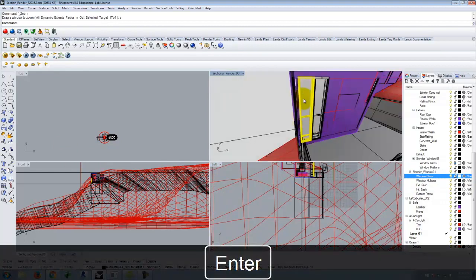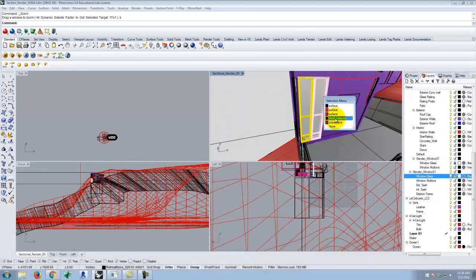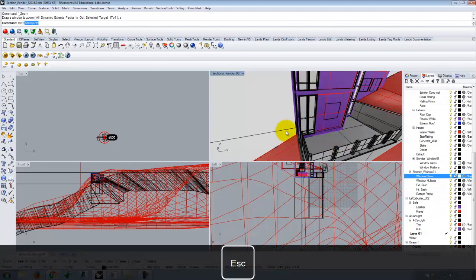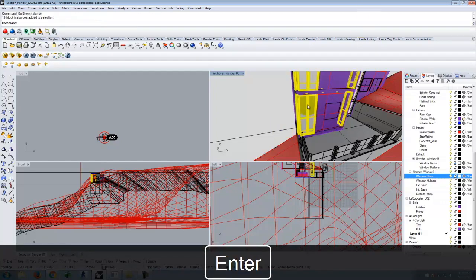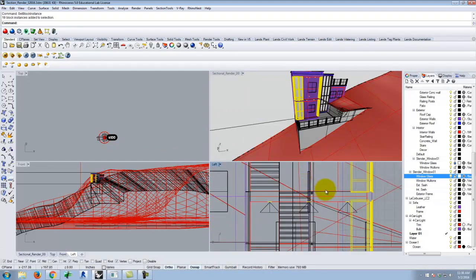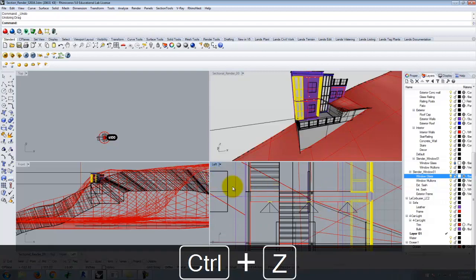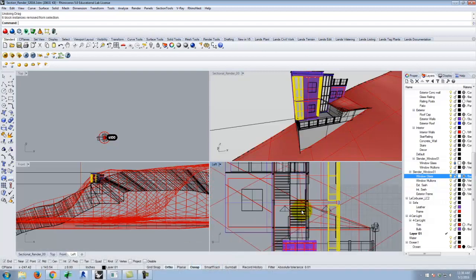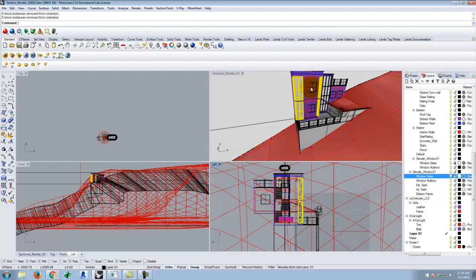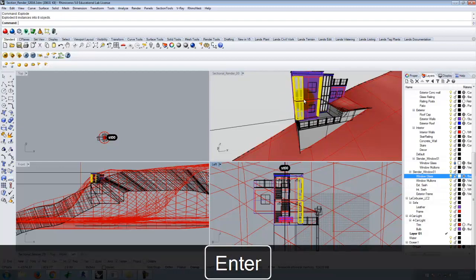Zoom selected. Actually, you know what? Let me just do SEL block to select them all, which includes my light fixtures and my windows there. Let's deselect my light fixtures. Oops. Come on. It wouldn't harm them, but I don't want to have to deal with them, so I'm not going to. So now those are selected. Let me explode. Now those are exploded.